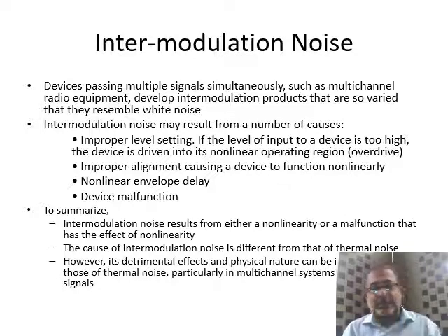Secondly, improper alignment causing a device to function non-linearly. Thirdly, nonlinear envelope delay would also cause intermodulation noise. And fourthly, the device malfunction can drive it into a nonlinear region where the production of intermodulation noise because of intermodulation products is imminent.